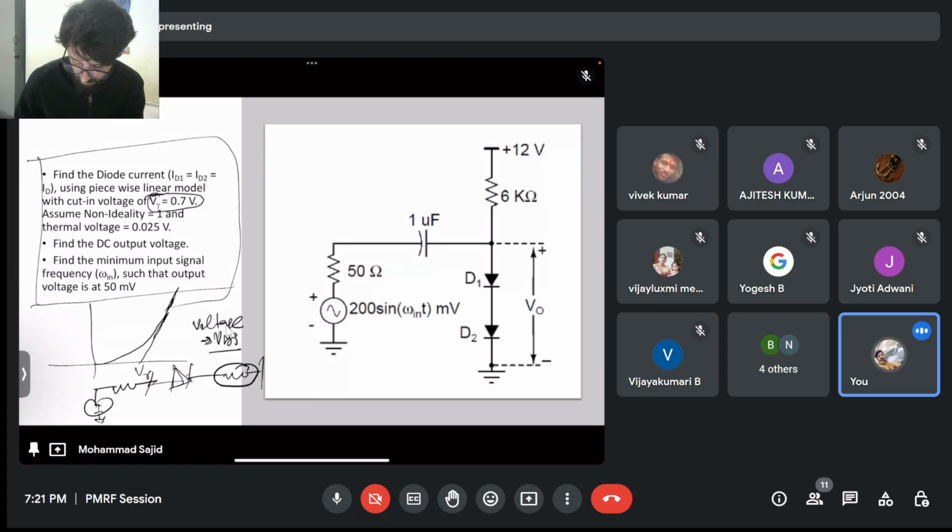So don't assume you have all the voltage across the diode. The diode can only handle its built-in voltage. You have seen a single battery of 0.7 volt; you just replace the diode with 0.7 volt. That's what is meant by saying there won't be more potential across the diode. The maximum potential of the diode is the cut-in voltage.